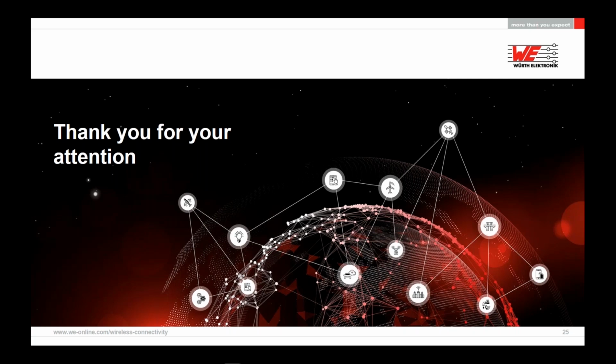Hello. So it's quite simple. The overhead of the header in a proprietary protocol is much smaller than if you have a non-proprietary one. For example, if you have a Bluetooth or a Wi-Fi protocol, there is a lot of data sent besides the payload. And on the proprietary radio, you mainly send addressing data in the header, but the remaining part is the payload. Yes. Okay, interesting. Many of these complex protocols actually have a very big overhead, and we tend to reduce this. You could, in fact, use different addressing modes, which could also affect the overhead size.